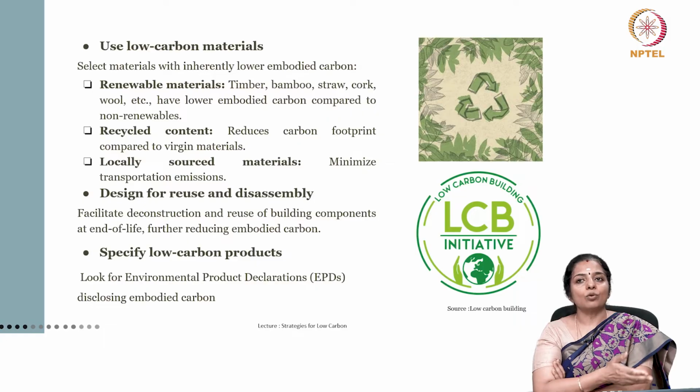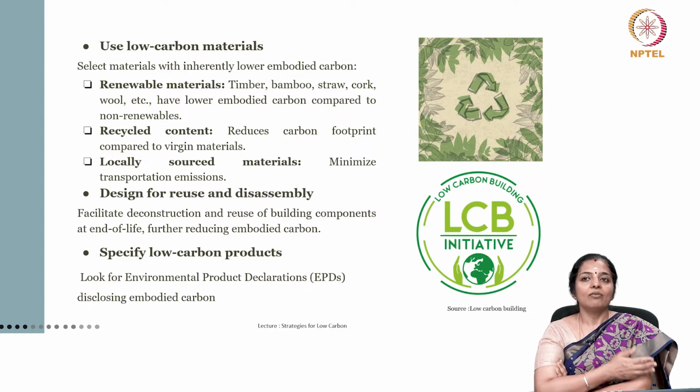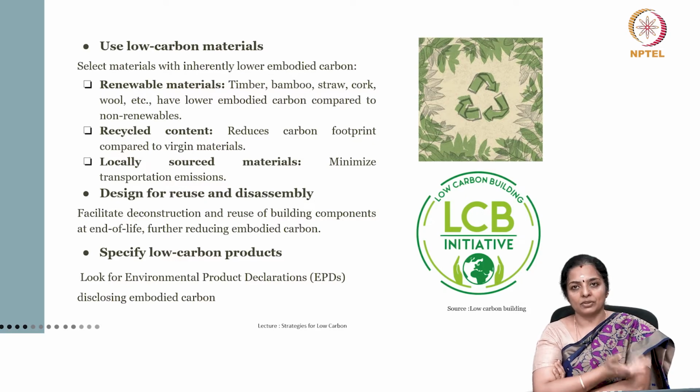Now, steel sourced from an electric arc furnace and made with high recycled content will have a lower overall embodied carbon as compared to steel which is got first time. Then you can also consider design for reuse and disassembly.